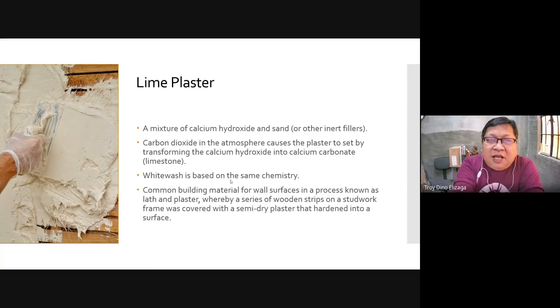Another one is lime plaster, which is also used in tabique Pampango construction, or tabique construction. So with the wood lath, lime, sometimes they call it lime slurry. Right now, in restoring some of the old churches, I have to deal with this material, but it's not easy